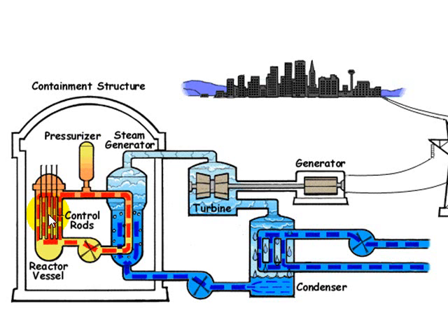The beta particles have very limited range and are easily stopped by the walls of the reactor vessel. Neutrons and gamma rays, however, produce very little ionization and therefore are extremely penetrating. As a consequence, extremely thick walls are placed around the nuclear reactor. These walls are around about 5 meters thick and are made of concrete. This protects the personnel who work in the vicinity of a reactor.